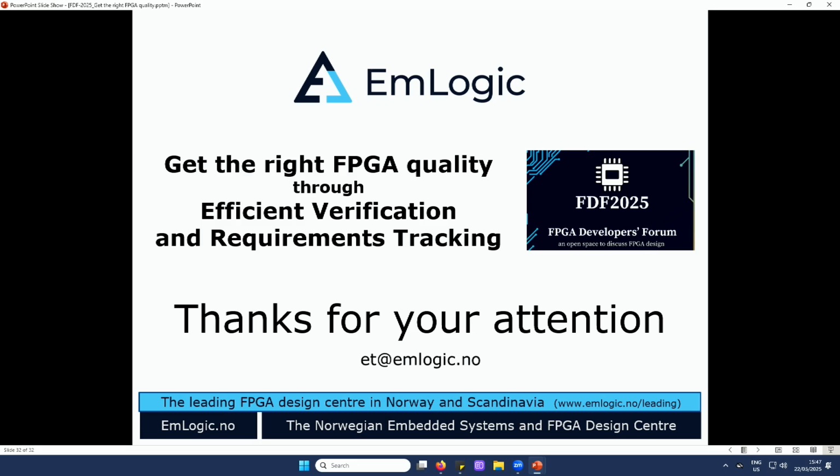If you have a design where you could have a contention, that is, there could be problems when you, for instance, apply data on one interface at the same time as you apply data on another interface, maybe reading data out on a third interface, then you should go for the verification components. They allow you, from the test sequencer, to send out commands to every single verification component so that they can all start at the same time.